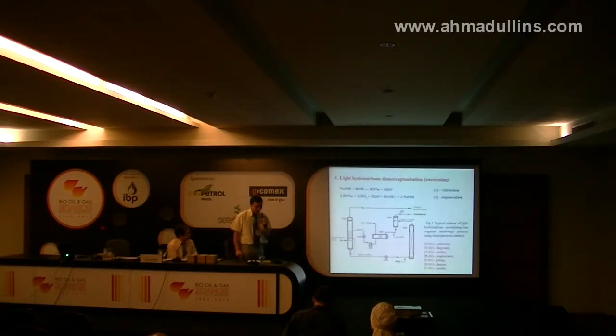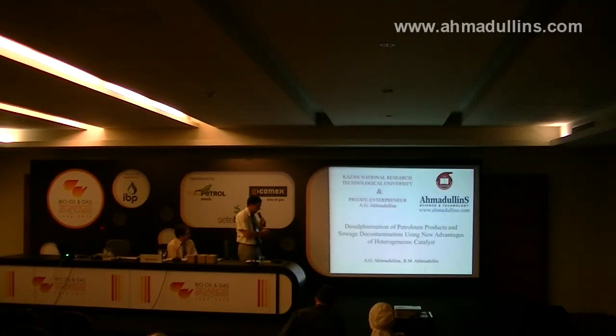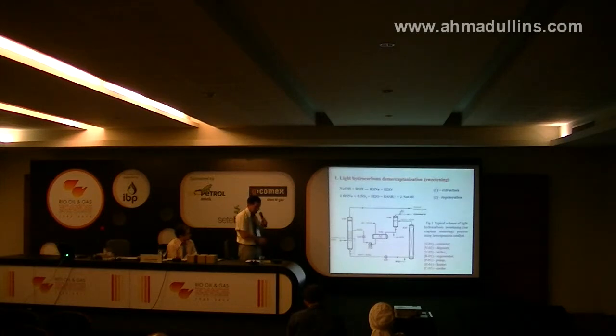This confirmed the occurrence of mercaptan oxidation in the alkaline catalyst solution outside the regeneration, in the pipelines or in the extractor itself. A similar result using a process with a water-soluble alkaline homogeneous catalyst had been obtained in the Iranian refineries.